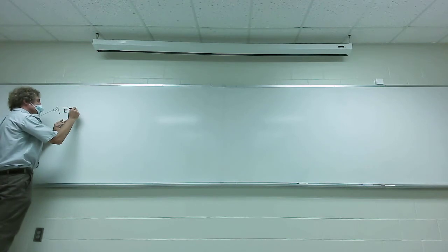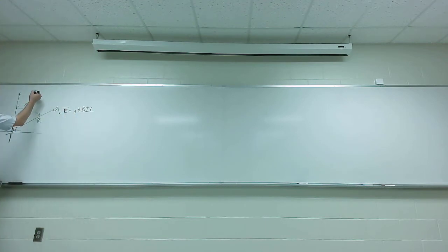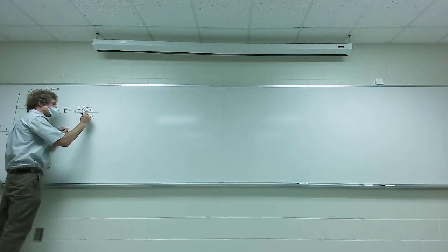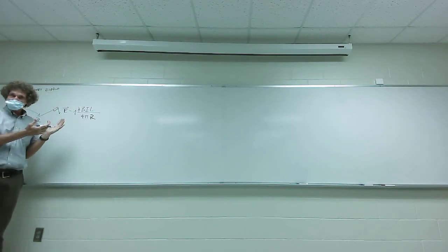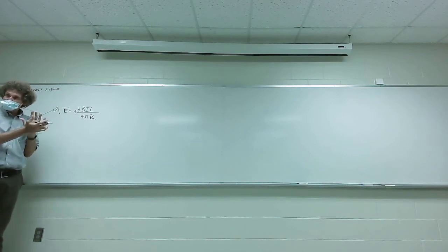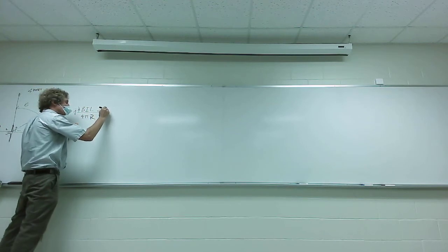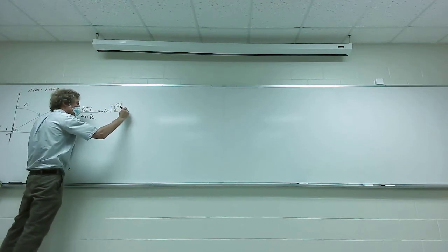So E would be equal to j eta beta times I times the length L of the antenna. And this will be for a short dipole. Then it's going to be divided by 4 pi r. Now there are different formulas. I'm going to show you another one in a second. All have the same essence. They always will give you the same values, but there's different forms of this. Then it's going to vary as the sine of the angle theta, and it will be times e to the minus j beta r, a theta.